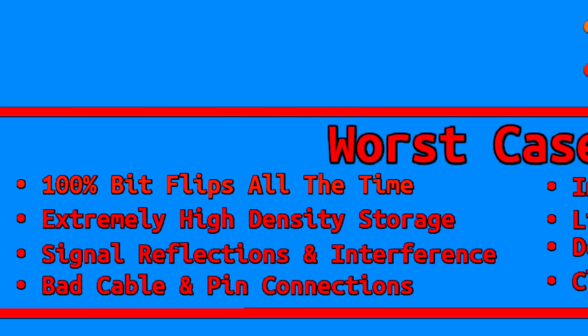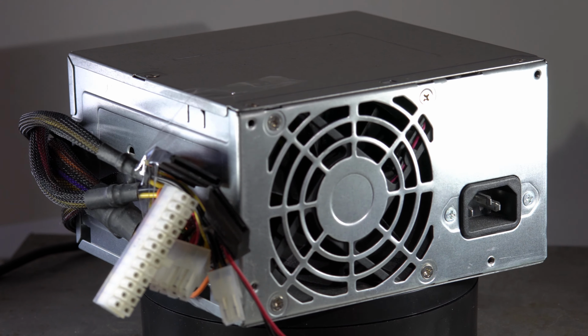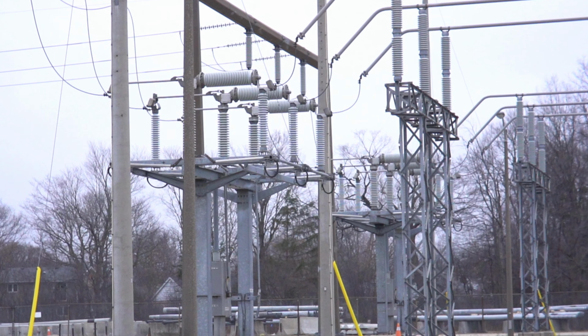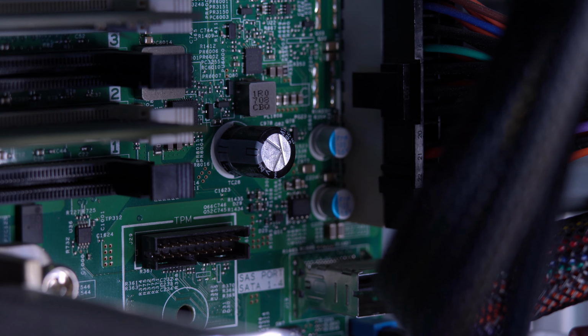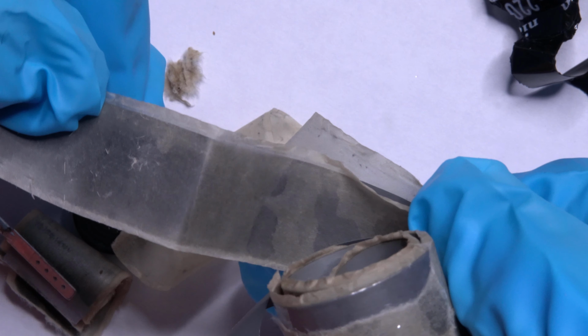This computer is in really bad shape. It has all of the following problems. First of all, it's overheating, and it's way above normal operating temperature. It also has a bad power supply that produces lots of ripple, undervoltage, and overvoltage. It would also have problems with the input power that comes from the power grid. The power grid would be experiencing problems like voltage sags, voltage spikes, or frequency and phase shifts. All of these glitches in the input power would eventually make their way to one of the pins on the RAM stick. The motherboard and power supply would also have bad capacitors, likely from the electrolyte inside of them boiling off due to prolonged overheating.